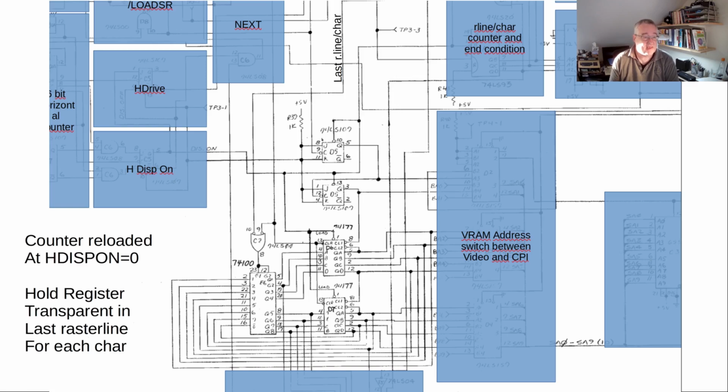It counts 1 up. And there's one peculiarity with the JK flip-flops: if both inputs are high and you have the clock running, the output alternates. Goes from 1 to 0, 0 to 1. So this is basically a counter. This goes into the next one, which has the same setup. J and K inputs are both set high. Those are the first 2 address bits, and the reason they can do that is because all the numbers in the timing are divisible by 4. So those actually don't really matter much. You don't need to reload them.